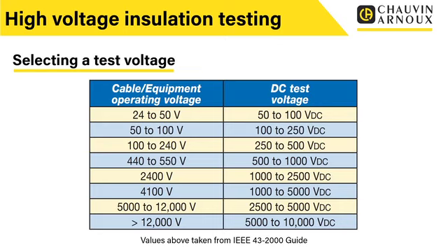So we need to put it under sufficient stress to be able to detect any weaknesses within the insulation. But what we don't want to do is put too much stress under it that's actually going to damage it. Remember, we were saying this is a type of non-destructive condition testing. We're not here to try and break this. We're not putting it under stress to break it down. What we're trying to do is use enough voltage to be able to actually determine its condition without causing damage.